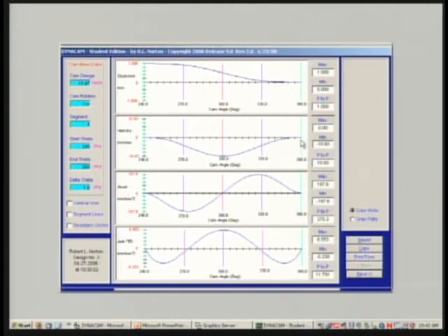Velocity looks a little bit like it did before, but it's very flat at the ends here, and the reason it's flat is we told the acceleration to be 0, and we also told the jerk to be 0 there. And when I pin those down, this jerk is the slope of the acceleration, correct? If I tell the slope to be 0, then the slope is 0 here. If the slope is 0, then it starts off with that 0 slope, let's come in from the front end, and then climbs up to a higher value of peak acceleration than I would have had in the 3, 4, 5. By the same token, tying this jerk to 0 at the beginning further flattens the velocity.